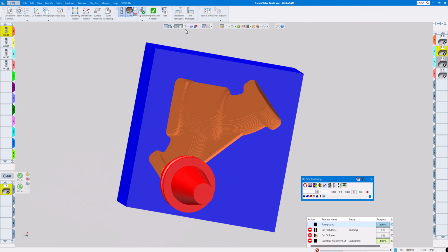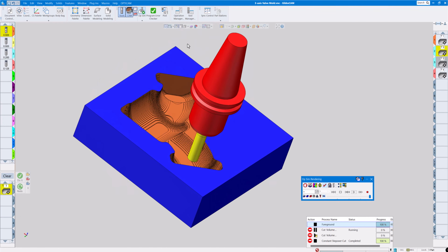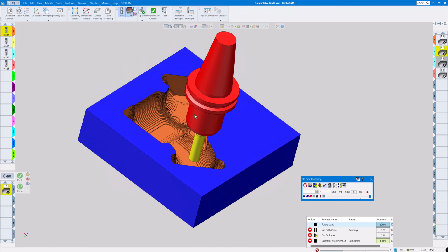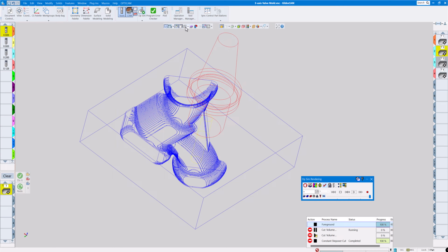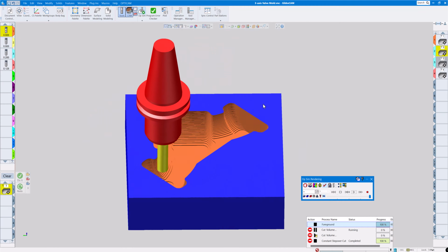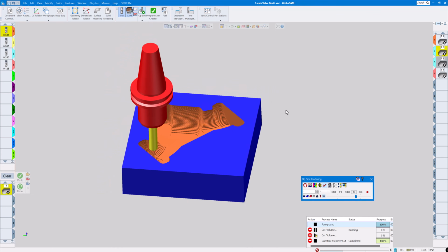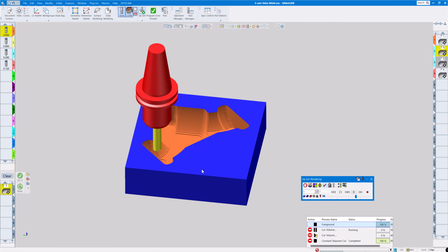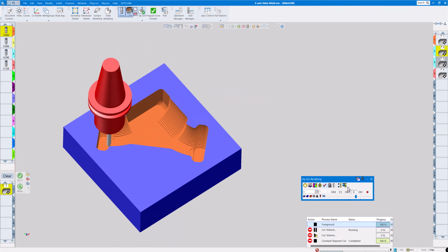If you want to turn this on, you can see the steps a little bit more there. It shows more of a wireframe of the steps. And then you can choose to have these here, which I don't use very much. Then back to the solid. So the next thing we're going to do is, of course, the finish. That's with the 1/4 inch ball end mill, starting from the inside out. So let's render that.